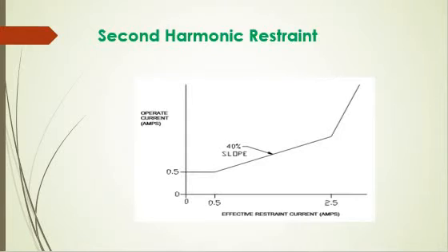On microprocessor based transformer differential relays, the restraint for magnetizing inrush is achieved in a different way. The shape of the waveform is analyzed by the microprocessor to determine if magnetizing inrush current is present. The operating characteristics of a transformer differential relay are shown here. Note that the pickup current of the relay increases with the amount of through current. This slope is shown here.